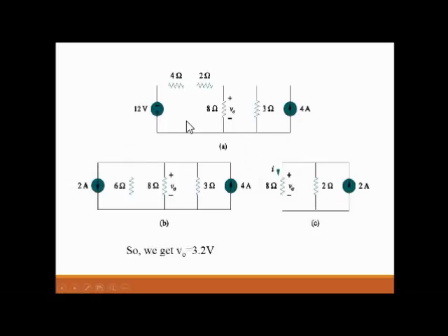So we can convert that current source along with the parallel resistor to a voltage source and the same resistor in series. Now see how easy it has become. We only have two voltage sources, some resistance and a simple current source. Now by taking the equivalent of all these resistances, you get 6 ohm, 8 ohm, 3 ohm in parallel with two opposite current sources.